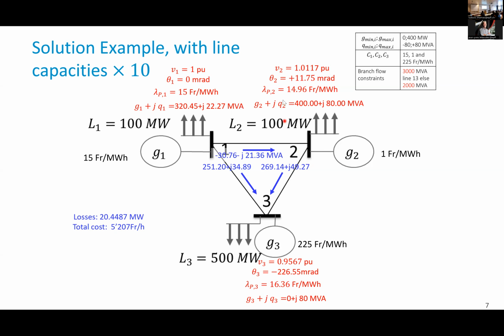So we see that by controlling the power flow, we are forced to accept the values of the voltage here. It's impossible to have voltage equal to 1 everywhere. If we had this, there would be no power flow anywhere. So we must have voltage differences for power to flow, but the voltage differences also mean potential voltage problems and potential ampacity problems with the level of the currents in the line. That's exactly why we need OPF.